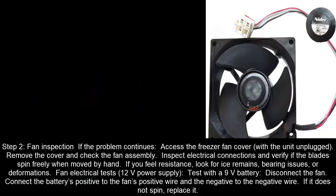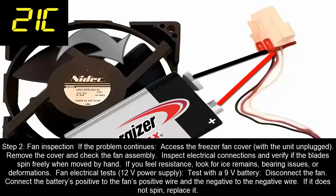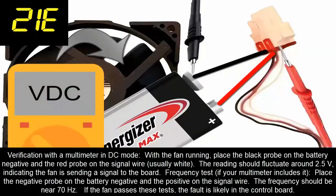Fan electrical tests. 12-volt power supply. Test with a 9-volt battery. Disconnect the fan. Connect the battery's positive to the fan's positive wire and the negative to the negative wire. If it does not spin, replace it.